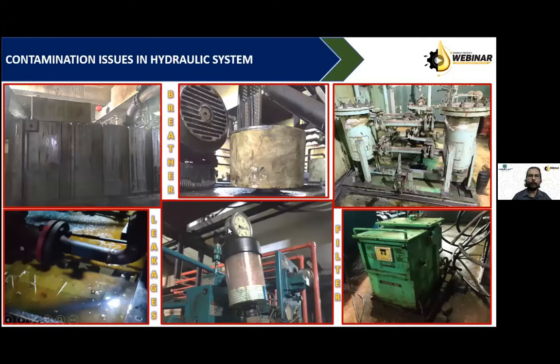We can see some real-time pictures. When we visit the industry, we see the condition of breather. Normally, breathers are the most neglected part of the hydraulic system in general practice, but they are a very critical component, and they are vital for the contamination control in the hydraulic circuit.